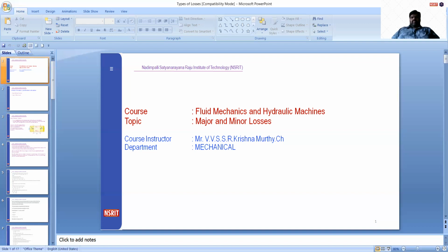So the total pressure forces acting are P1 A1 minus P2 A2, and in between these cross-sections there is a pressure P dash acting on A2 minus A1. This can be simplified as P dash into (A2 minus A1), where P dash is nothing but the inlet pressure P1. The simplified resultant force is (P1 minus P2) into A2.